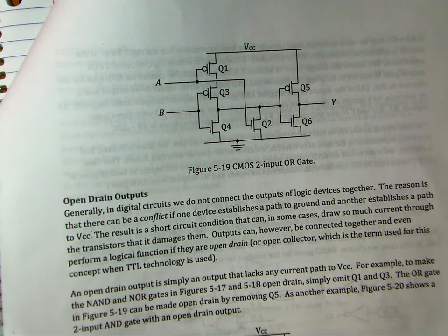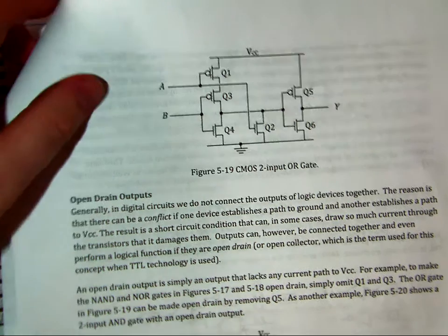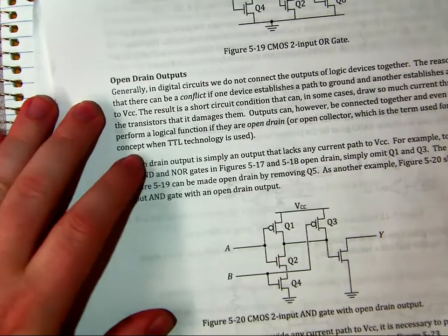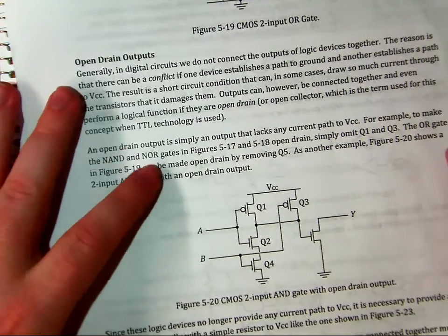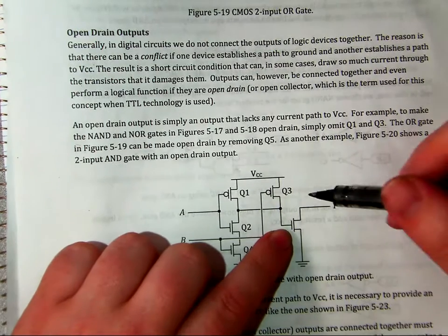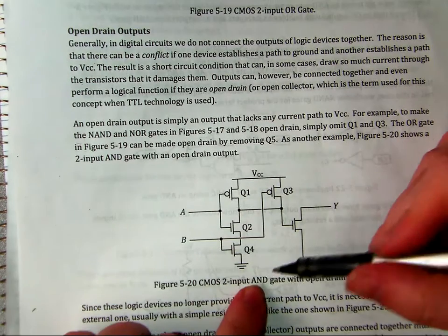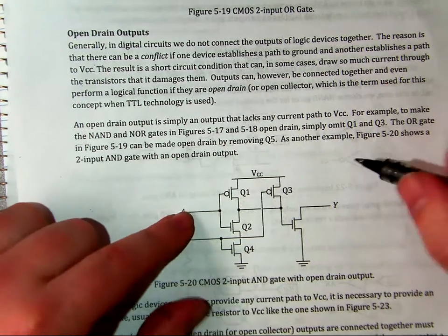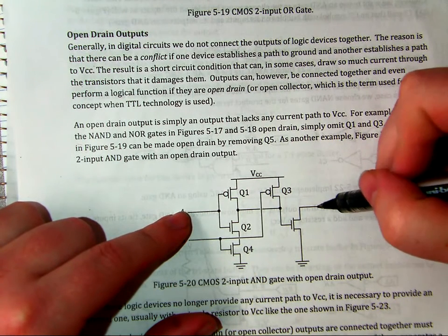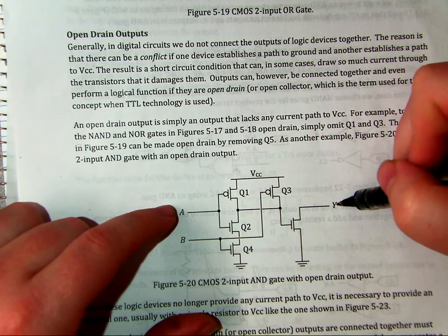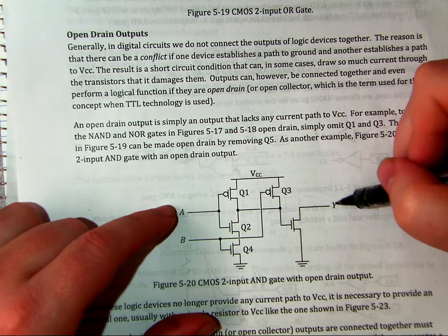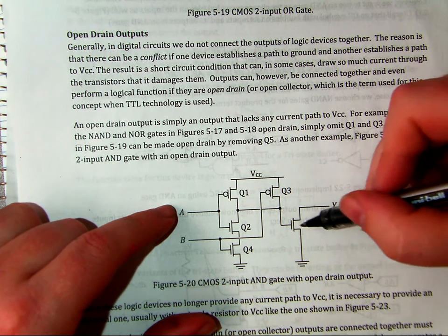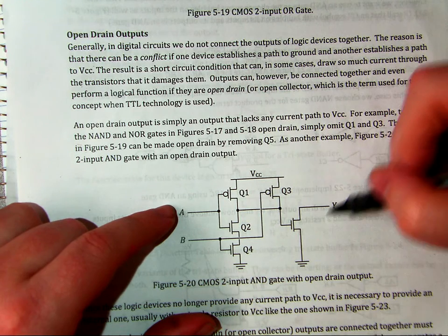Okay, so this is another idea that we need to get into once you've understood that's called open drain. Open drain are not used that often, but they will exist. And all that happens is on an open drain, let's only pay attention to this output. So this is an AND gate with an open drain. What this means is that this node here, you'll notice, never asserts high. There's no way for this node to go high. It can, however, be pulled low, right? Because there's no switch going up. There is a switch going down. So it is 0 or question mark.